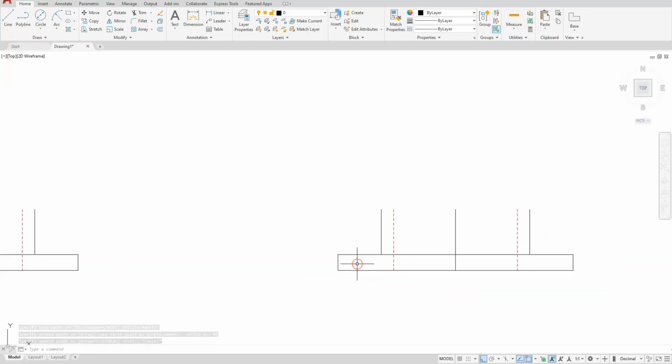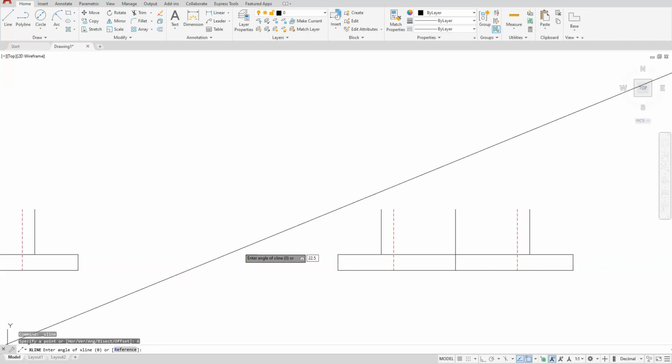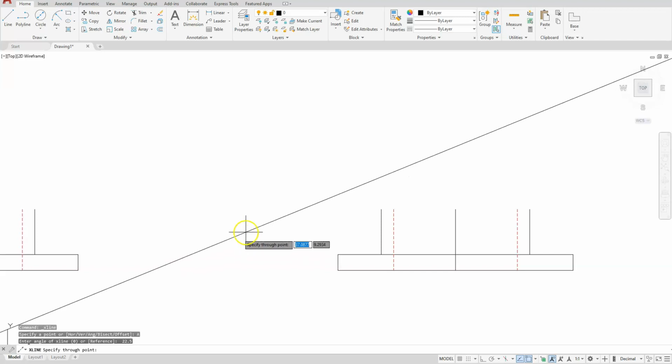Now I'll concentrate on this side. What I need to do is give this a mirror point in order to make this a 45 degree. It tells me on the drawing that away from this center here and up will be my halfway distance going across this elbow. Let's go ahead and create a construction line. Select the word angle. Put in the angle that I want it to be. In this case it's 22.5. Enter. Now it's asking me for the location.